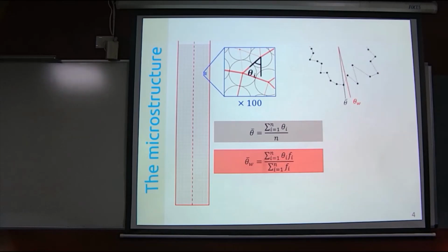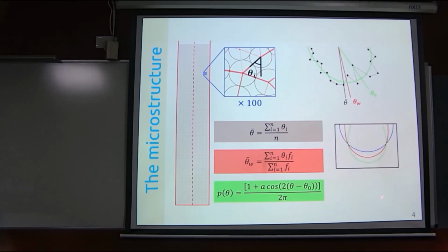All right. So even these two are not sufficient to adequately characterize the anisotropy in the system. This gives the angle of anisotropy. It does not tell anything about the magnitude of anisotropy. So for that we need to use this function to fit this distribution, where A is now basically the magnitude of this anisotropy. Right. So to understand it better, let's say there are these three kinds of contact angle distributions.